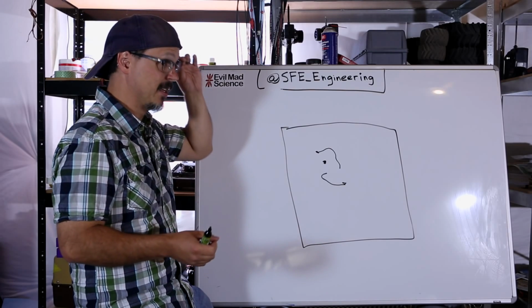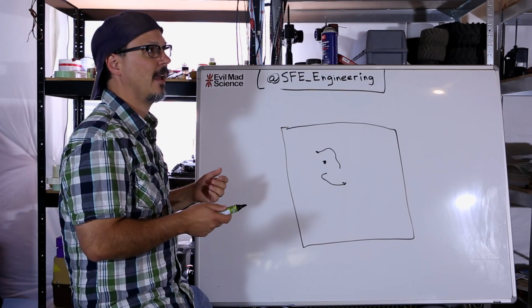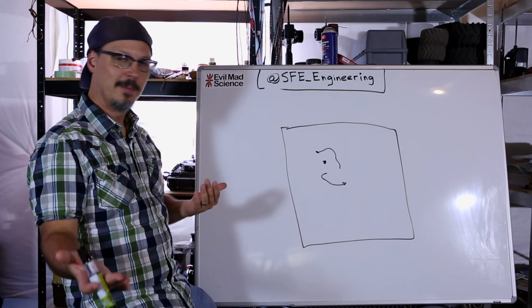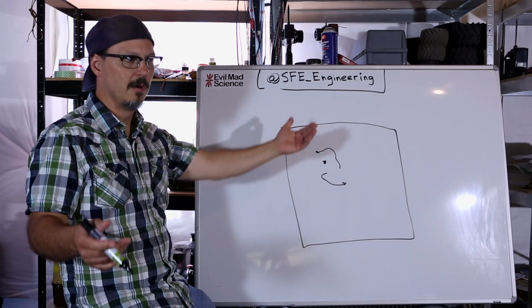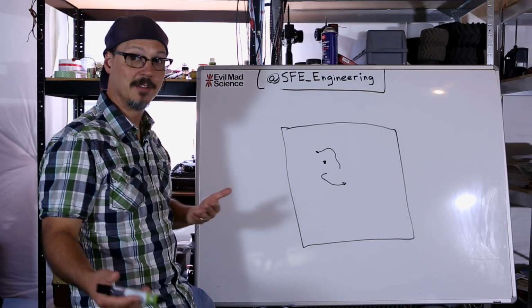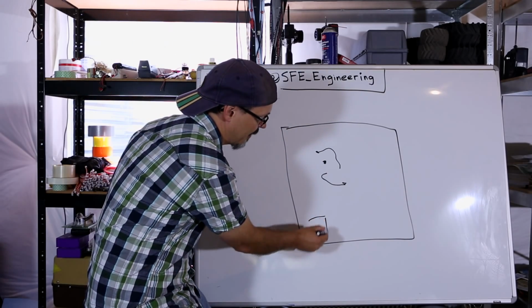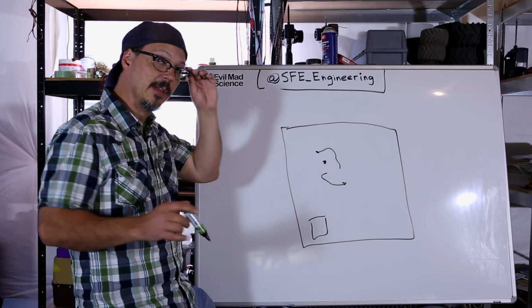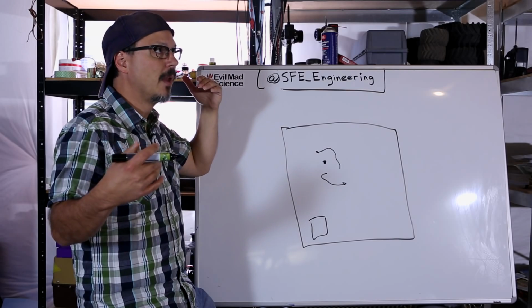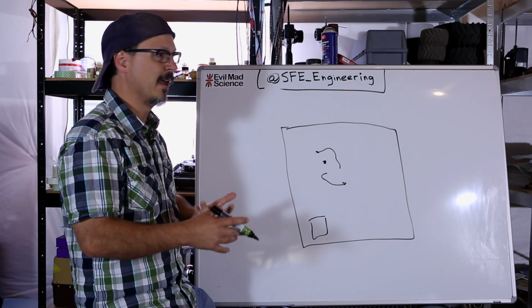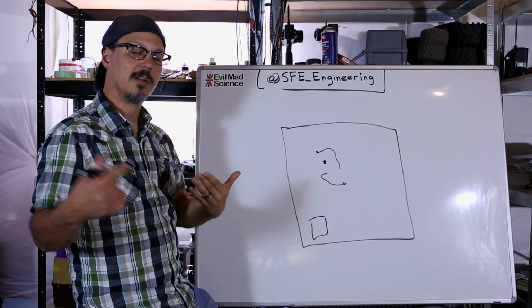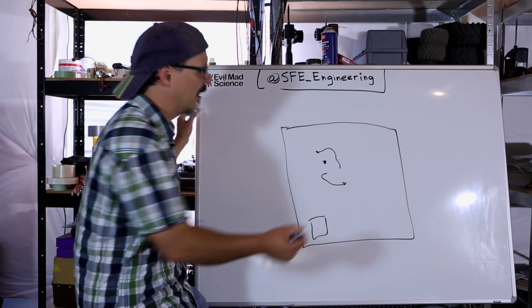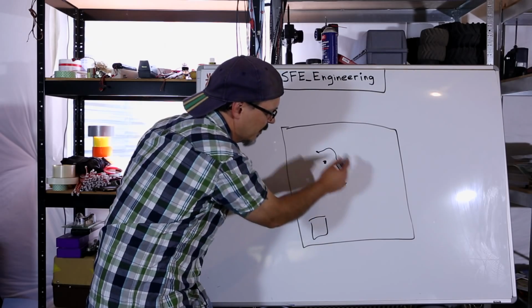It's not going to tell you, hey dude, your return path is stupid and you should fix it. What do I mean by that? The return path is where your current is coming back to the power supply, back to the regulator, for example, which in our example is down here, okay? So on all of my circuit stages, I'm going to be looking at how much current the stage is drawing and what the current path looks like. If it's a low current return, I'm probably not going to worry too much about it because there'll be enough copper here that it'll find multiple paths.